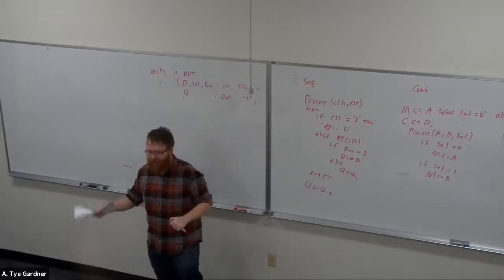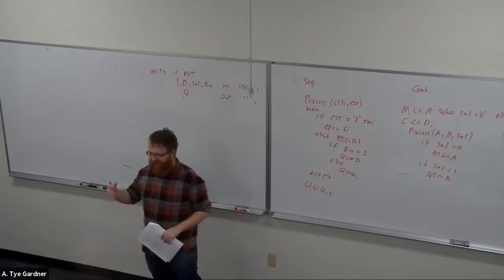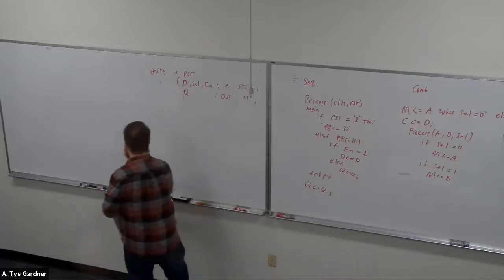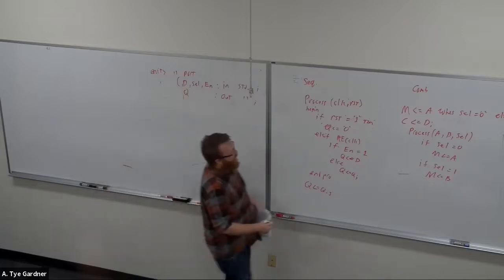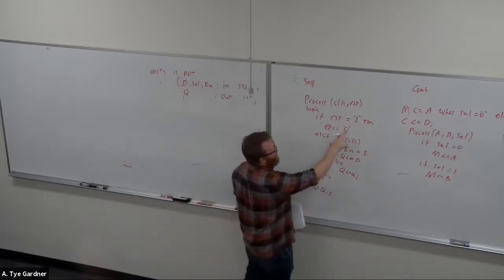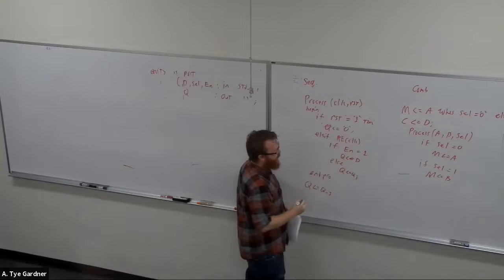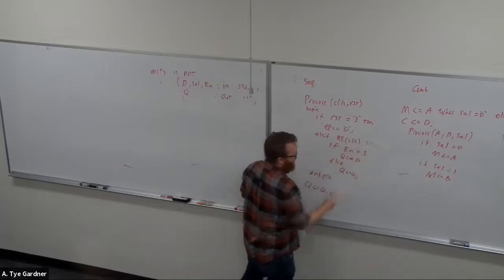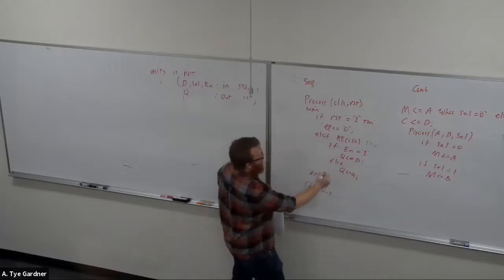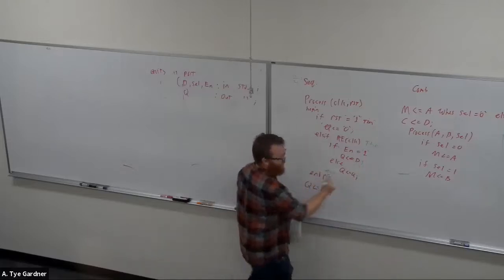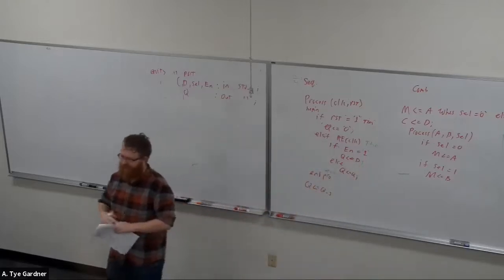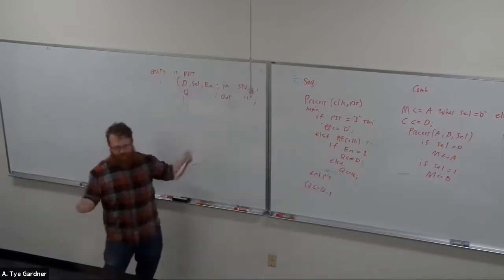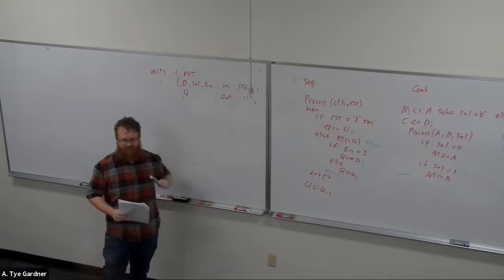So I don't expect you to know all of them, but you should be able to find at least many of them, right? So you would go through and be like, okay, well, that's a bit type, we forget a semicolon, else if rising edge of clock, I forgot a then, I forgot the apostrophes, I forgot a semicolon, I forgot the end ifs, right? Things like that. That would be the kind of example. This would actually be a perfectly fair question to have asked: given that code, correct the errors.